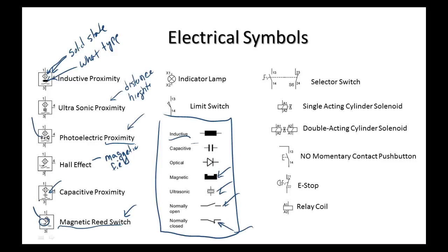But I have never seen a normally closed reed switch. I don't know how it would work, because it's got two metal rods coming out. When you put a magnetic field, basically you put the magnet in there sideways, so one side is the north and one side is the south. The magnetic field concentrates through both of the rods, and they actually pull themselves together. So you don't want to put just a north pole, and you don't want to put just a south pole. You want to put a magnet in there sideways so you see a north-south. That makes sense?